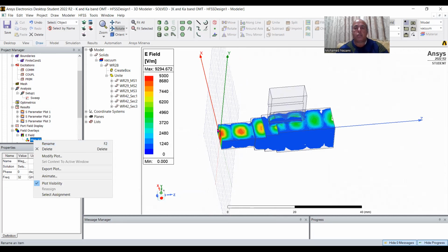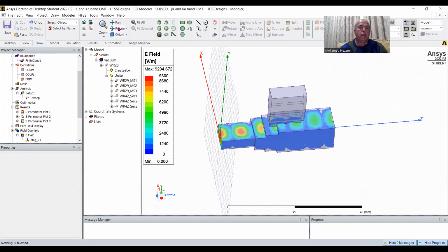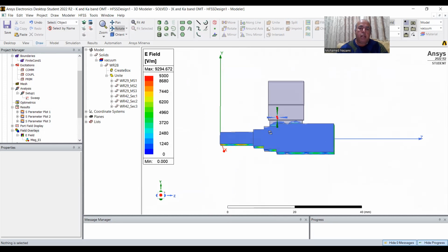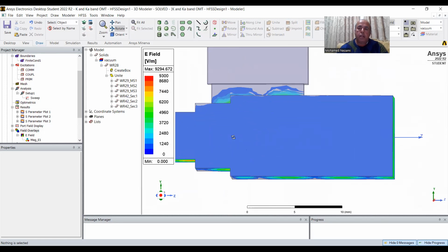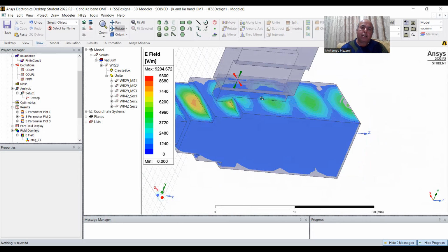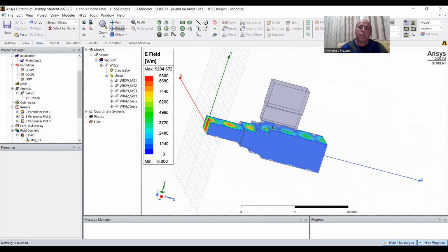Okay, so the signal is very hot in here, and as you can see, without even animation, the signal is completely going out to this side, and very little is leaking into the slot that goes into the receive path. Because this side here is attached to a 10-watt transmitter in a lot of cases, and even 50 and 100. So that's a lot of signal compared to the signal here. Like this might be 40 dBm, plus 40 dBm, while the received signal is like minus 110 dBm.